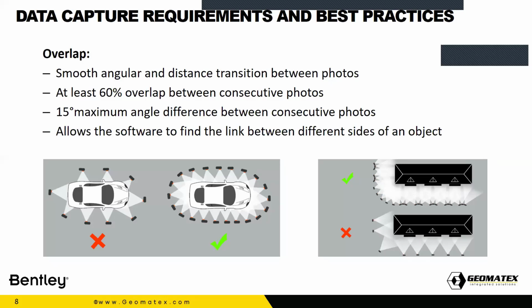They vary according to the level of detail I need, the nature of the object itself, the orientation itself, the accessibility. But as a concept, we should focus on the overlap. So here, from my perspective, I did overlap because I'm taking so many images, but the overlap depends on the focal length of the camera, which means that the coverage here is maybe not allowing me to do any kind of overlap.